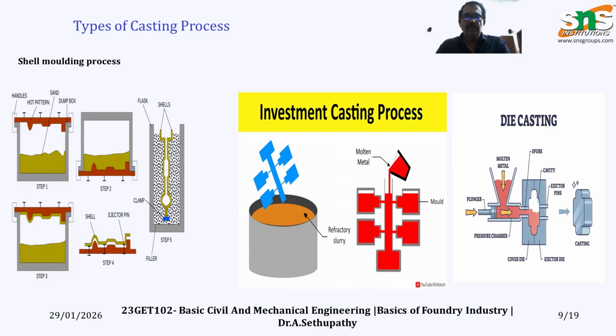Now we melt the metal and pour it into the shell. The shell has a gap inside, where the projections we need in the casting are formed. The metal is poured into the center part of the assembled shells and solidifies after some time.